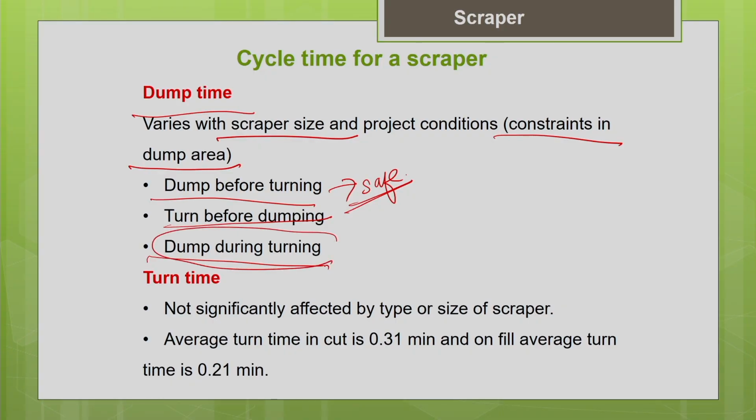Okay, sometimes you have to even go for the third option, dumping and turning together. It depends upon the space availability. But the best thing, the safe way, is you dump the material and then make a turn. That is really safe for the scraper.